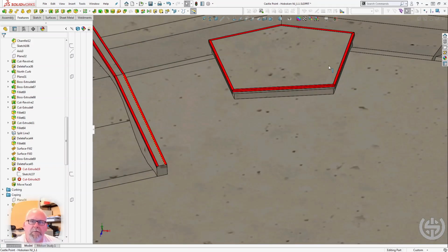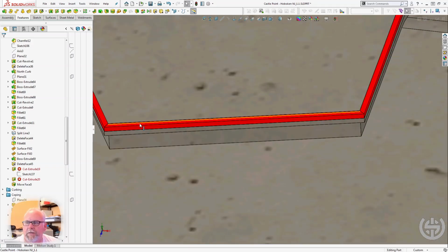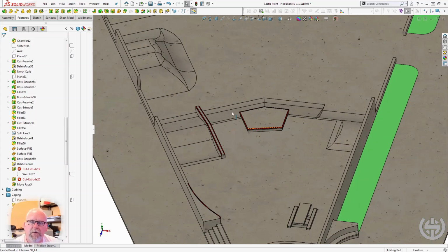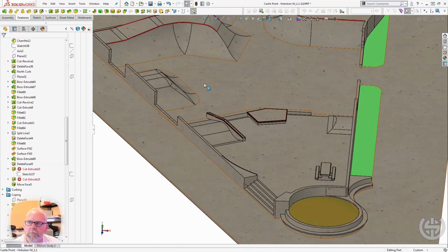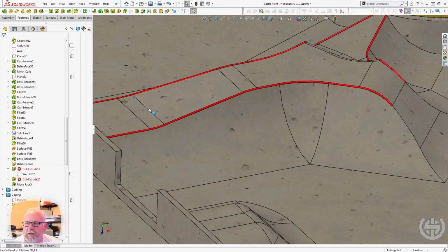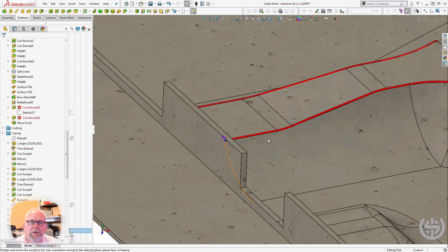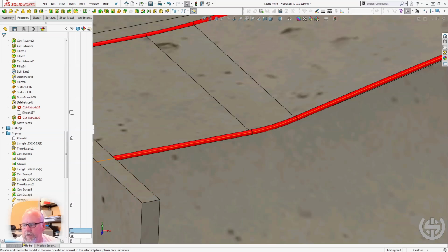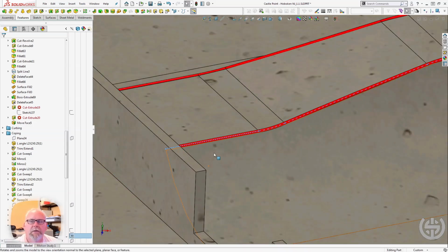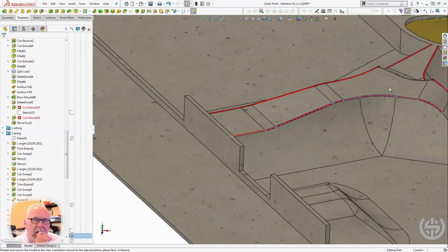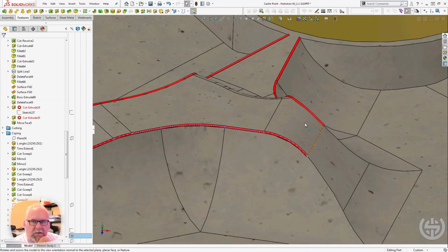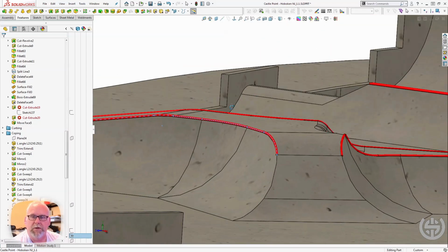So all this stuff, these are weldments, and I think this is 2x2 angle. So you can see that, and then this is either 1.5 or 2-inch coping. It's 2-inch. And I probably cheated and ran it right along the edge. I did. I didn't offset it or anything. So if I was doing this for real, obviously the coping would sit down and in. You wouldn't have it stick that far out. But it was just to mark the edges where the coping would be. So you can see where the coping would sit.